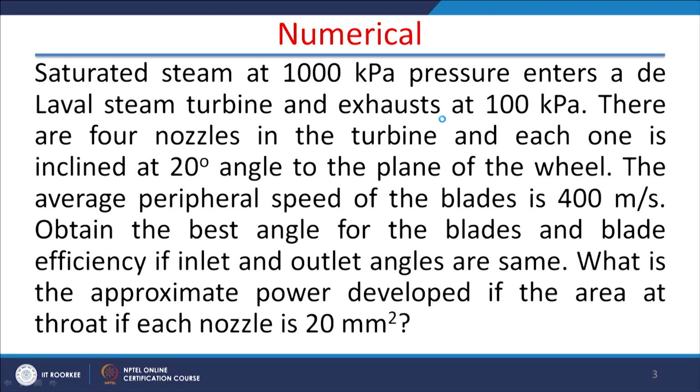So, later on you may not land up with some absurd value, say the diameter of the rotor is 50 meters. Rotor diameter cannot be 50 meters; the rotor diameter is a maximum of 1 meter. Or blade height is 3 millimeter; blade height cannot be 3 millimeter, it varies around 30 centimeters, I told you earlier. So these numericals are given. In the back of the mind you retain that these are the values which are close to the actual values, right.